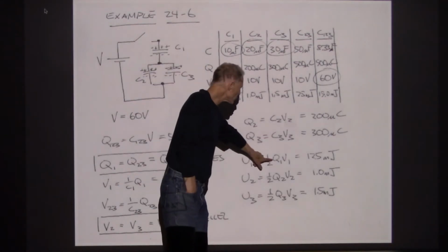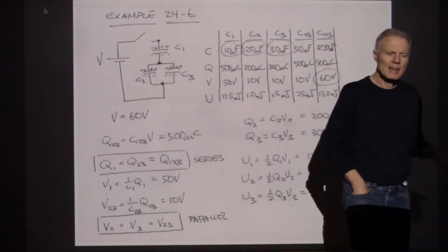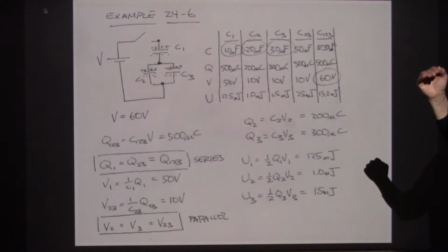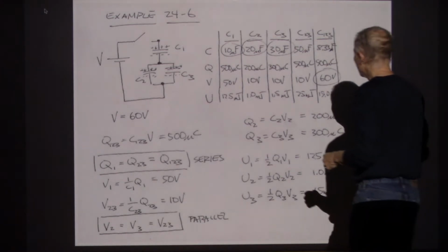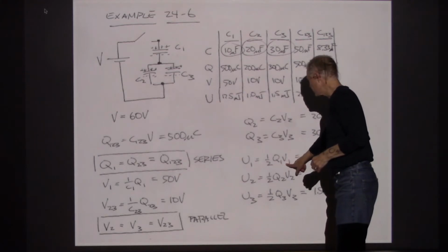But capacitors, when they charge, don't maintain a constant voltage during the time when they're charging. So a little bit of charge shows up first, and then a little bit more, and then a little bit more. And as a result, during the charging process, we only have a net energy storage of 1/2 QV.